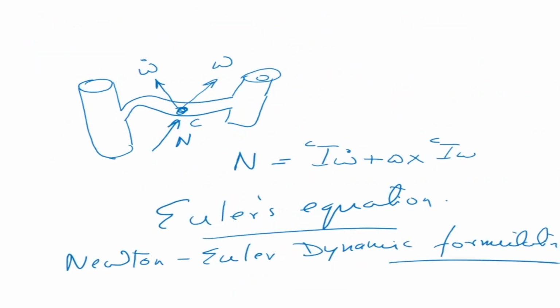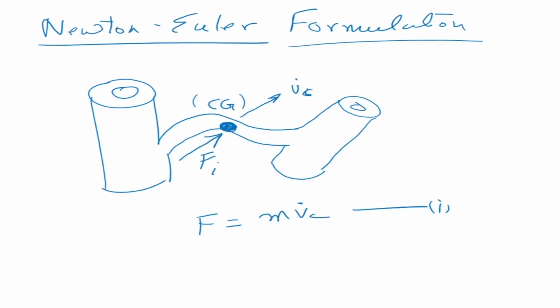This is the force-based method. What this tells us is that we have to find the forces acting at the CG of the link due to accelerations. We saw that when a link is moving, the velocities and accelerations propagate from link to link. From the base link it propagates towards the forward links, and those accelerations and velocities act at the CG of the link also. Based on that we can find the forces acting. Once we get the forces acting, we have to come backwards and find the torques acting at the joints because of these forces.